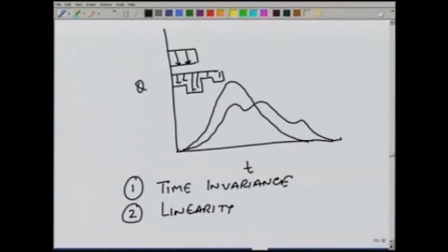For example, if the soil is very dry and rainfall occurs, a lot of it will go into infiltration and runoff will be smaller. For the same rainfall, if the soil is wet initially, for example, there was rain the day before, there will be more runoff. So, not even catchment to catchment, but even from one rainfall event to another, the hydrograph will be different.